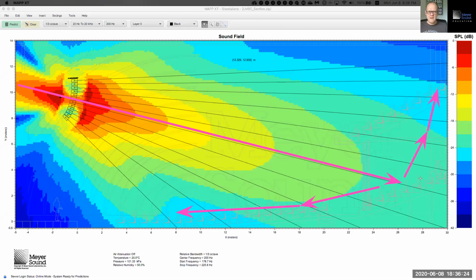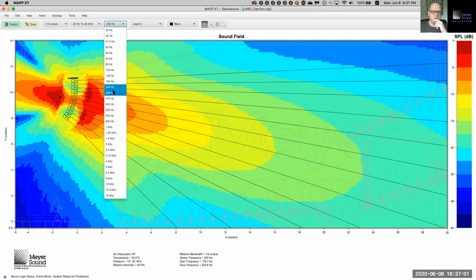So we have a beam which is too narrow. It's overshooting the first part of the audience, the first couple of rows. Then it's doing a nosedive under the balcony, and it's too narrow to have any substantial contribution on the balcony. And this is the problem that we're dealing with. This is basically your phase steering, your line length, which is the driving force at low frequencies, doing too much of a good thing, as we're about to discover. And then if we go up in frequency, then ultimately this beam will open up once more. Let's continue. Let's go to 250.